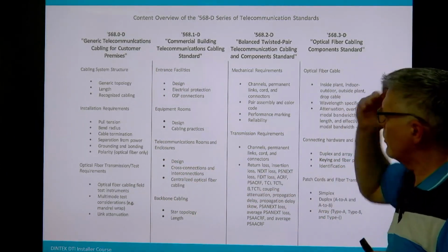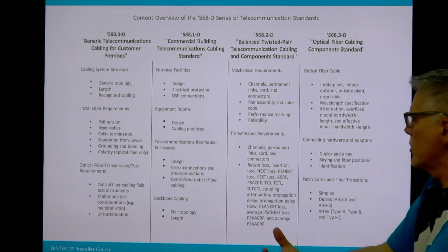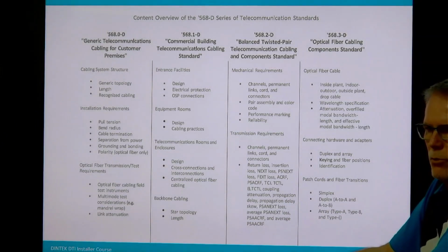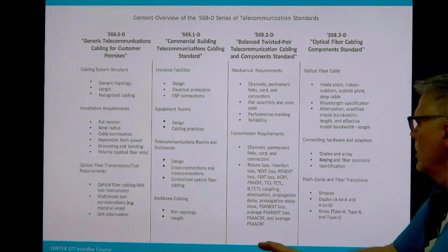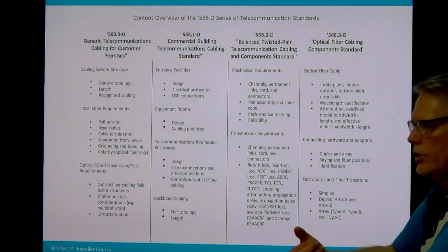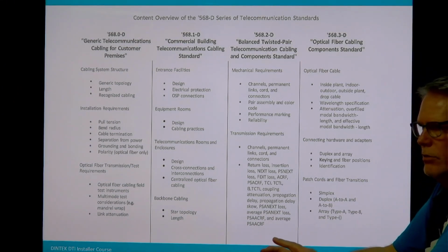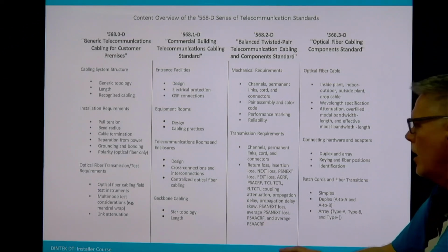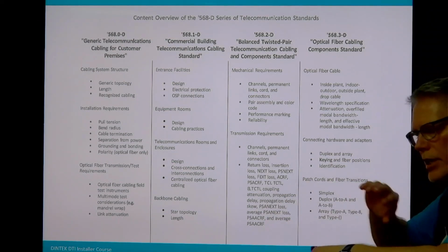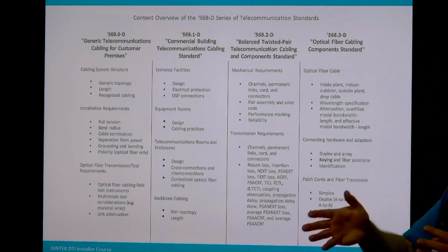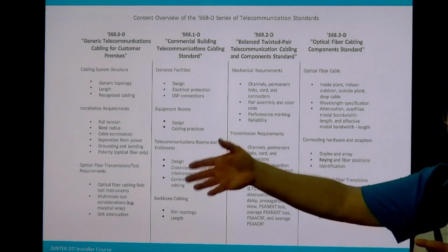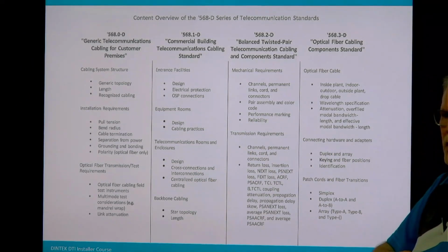So that's dealing with things like the generic topologies, length of cable, recognised cabling that we use, all the installation requirements, pull tension, bend radius, cable termination, things like that. That's the same whether it's a healthcare facility or a commercial setting.